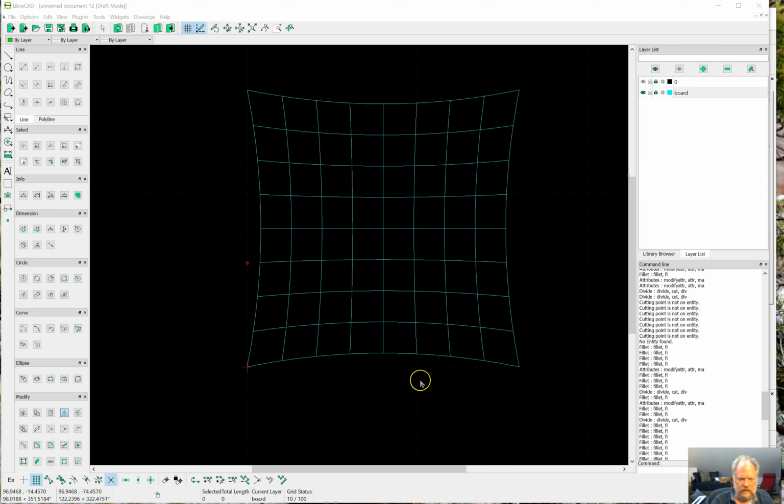Okay, I think I was successful in cutting them all up. I will say that I did make a minor mistake when I was originally doing this. I wanted to easily select these lines, so I had it set for snapping to some point on line. That actually proved to be a little bit challenging later on. You really only need to have the grid and the intersection, and that way it'll assure that you're always going to be cutting it at the points.